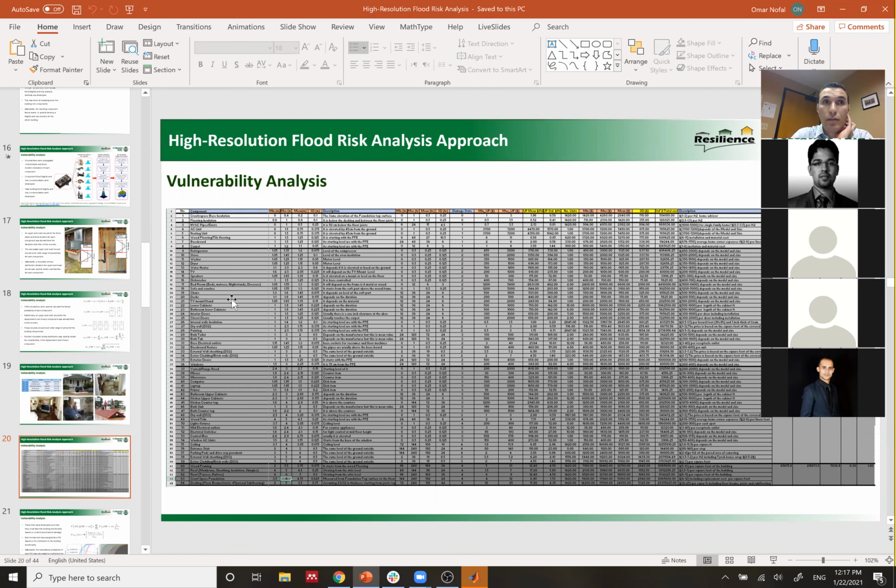It is in DS5. Yes, because the flood is 2 meters and your AC unit is at 1 meter, so it's completely damaged. And actually, we have uncertainty. If the AC unit is at 1 meter and you have a flood depth of 1 meter, we don't just say that our AC unit is at 1 meter; we run a 1,000 simulations with varying elevation of the AC unit.